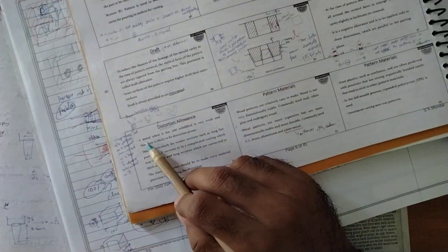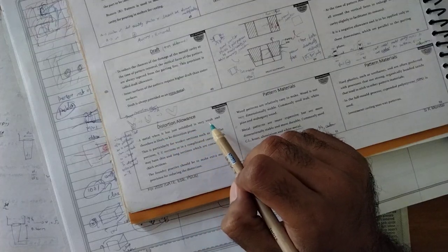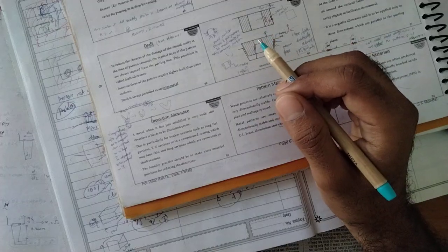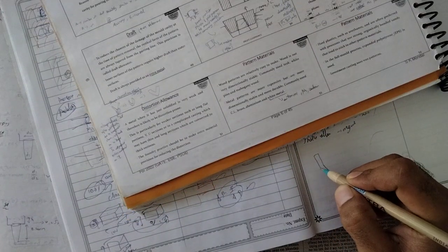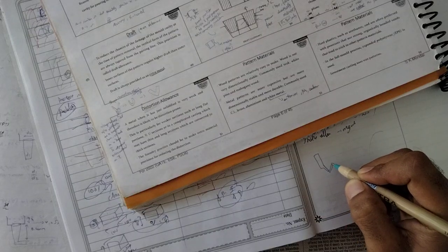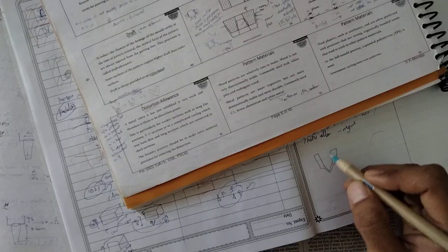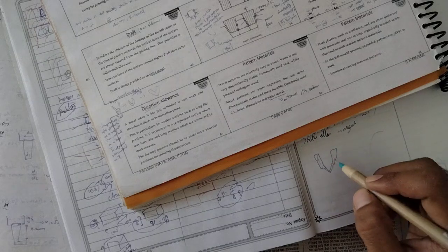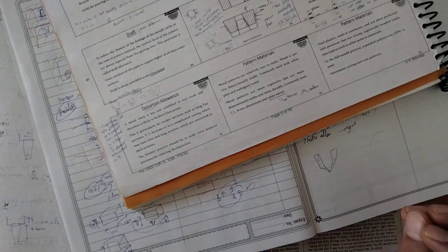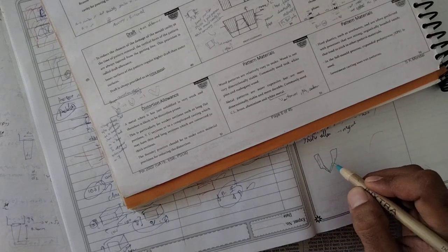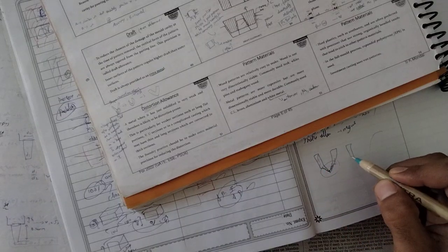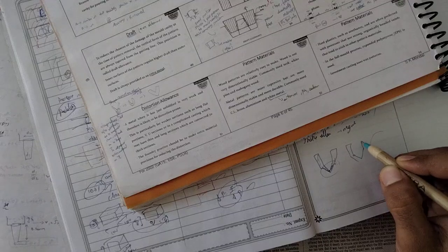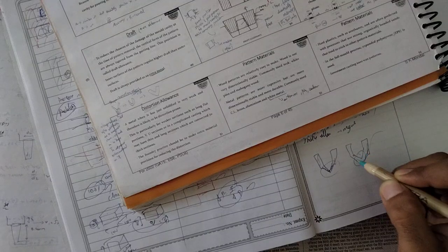Distortion allowance: a metal which has just solidified is weak, so it is likely to distort. For example, let us say the portion here is weak. While pouring, the metal fills every part here, but during the solidification process, while contraction pressure is going on, things get problematic and it can break easily. So we'll increase the cross section here and later machine it.